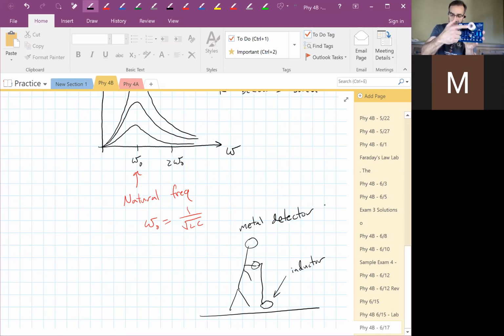And this is the inductor that we used, and it's marked over here, 8.2 millihenries. But over here, there's an iron bar. You stick it in the hole there in the inductor, and you've just changed the inductance quite a bit, because it responds very differently now to current. The inductance is very different now.